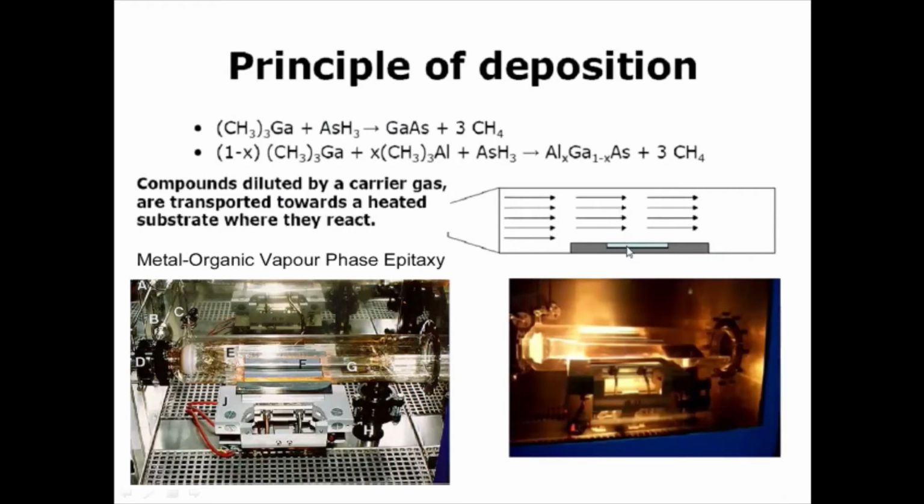You also get the composition of the deposited epitaxial layer on the substrate. So inside the reactor, you may have either convective flow or, depending upon the temperature, the radiative parameters will also come into the picture. If it is a convective flow, then the convective currents will create composition gradients, or the pyrolysis reaction will be different for different species. So you have to initially calculate, for this particular reactor geometry, what the flow characteristics should be, considering the material you are trying to deposit, right?